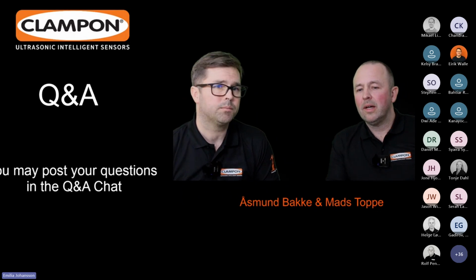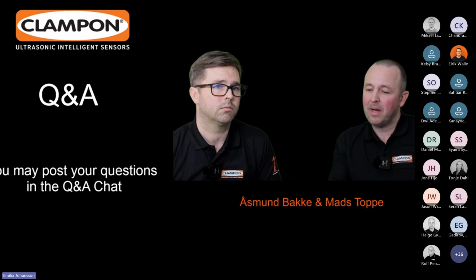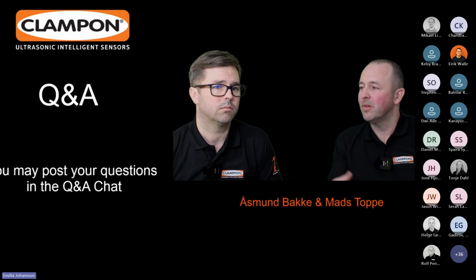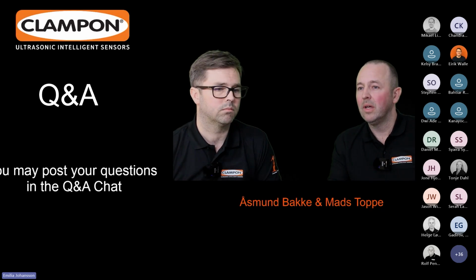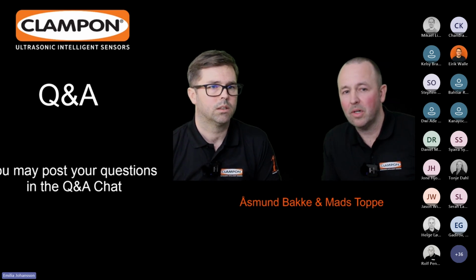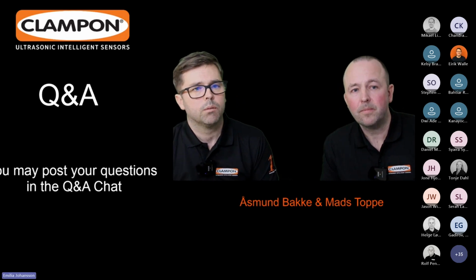But I also think that when you look at the sensitivity of the sensor, it can detect extremely small amounts at very low velocities. The challenge is to make sure that you have the zero setting correctly. So the auto zero will help you avoid situations where the previous sand monitoring software might have been masking out that type of sand production. Yeah, that's true. Will you take next, Mats?